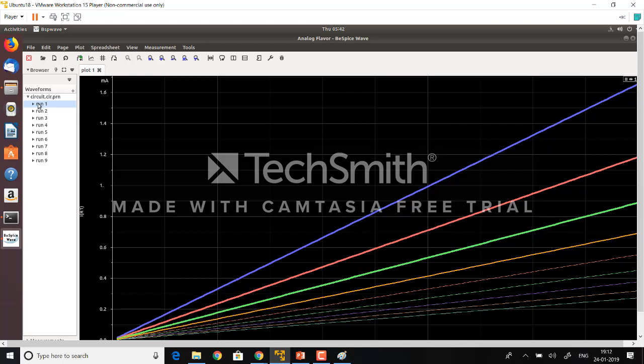The last thing I want you to see is self-heating. Okay, we defined it yesterday. Now, what is self-heating? Once current starts flowing through your device, it starts heating up. So your temperature goes up, then your resistance increases. So your currents go down.